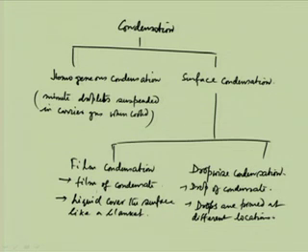We will come to that, but one thing we should say is that film condensation happens for a liquid which can wet the surface. So, when we are considering the condensation of some vapor, and the liquid which is formed is able to wet the surface on which it is condensing, then we can say that film type condensation will be formed.